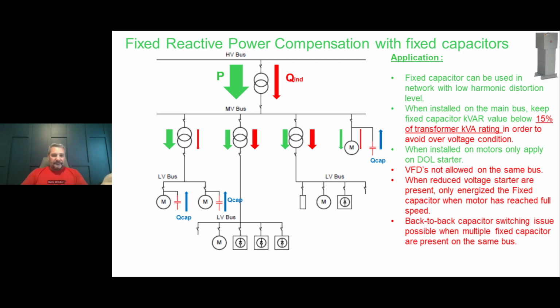But if you don't have much non-linear load in the system, you have a couple of motors that are creating poor power factor, then to put a fixed correction capacitor on the motor, it's not a bad practice still today.